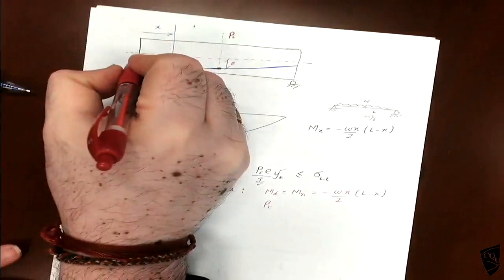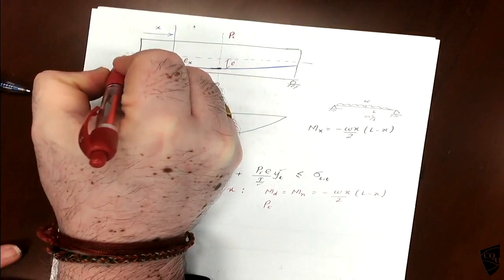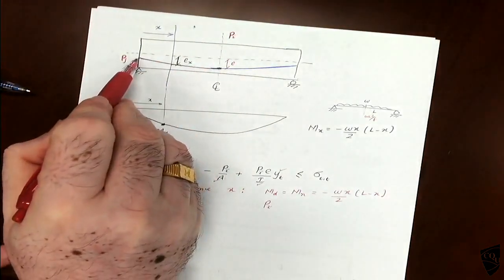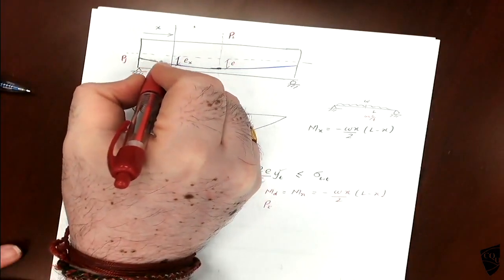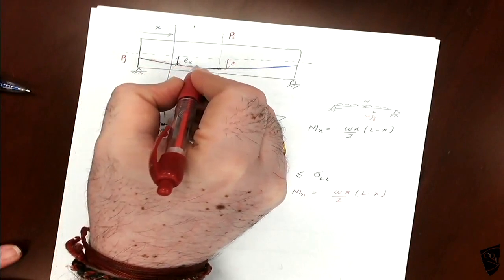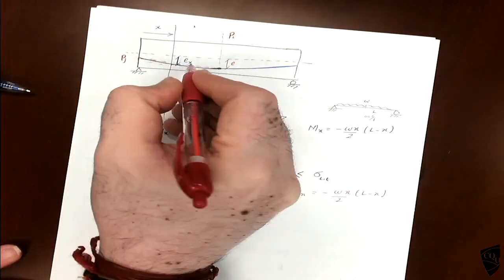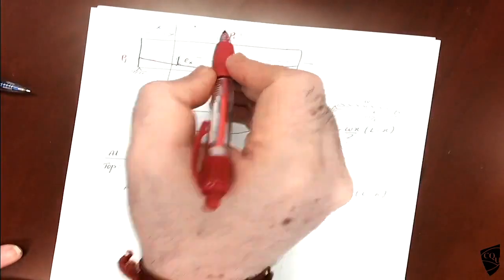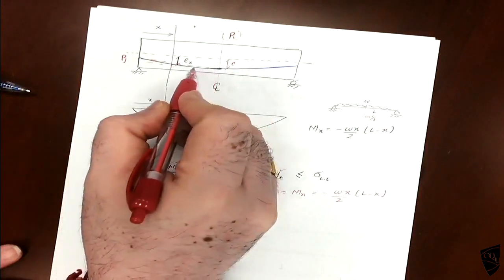So here we found Pj, the jacking force. We need to apply some extra force because there is a friction loss. We discussed yesterday that if we want the Pi here, this will be slightly larger because of the friction loss.